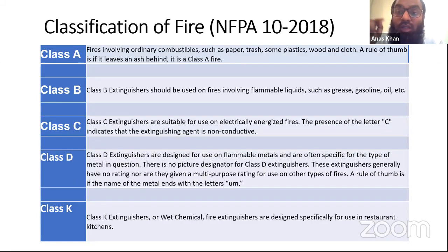In case of DCP powder, the gauge is not with the nitrogen. The gauge is with the powder. If it is full, then the gauge will show us full. In case of water, the gauge is with the water. Even in water, there are two mediums, nitrogen and water, because water cannot go out unless you push it by any force. So this is the nitrogen again.